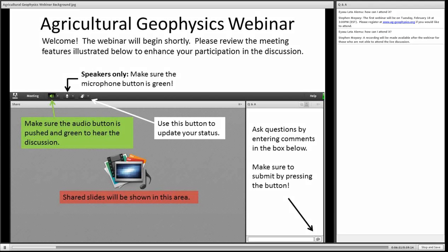So the key is what inhabits the fractures and structural features of the limestone. If it is conductive pore fluid, then EMI would work, not the short arrays that we tend to see with soil mapping, but arrays of separate transmitters and receivers held about 10 meters apart would be the tool to use.